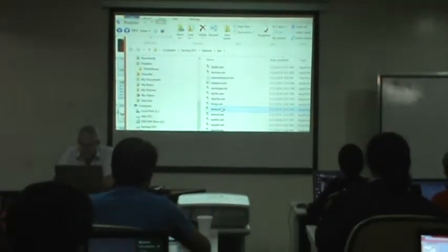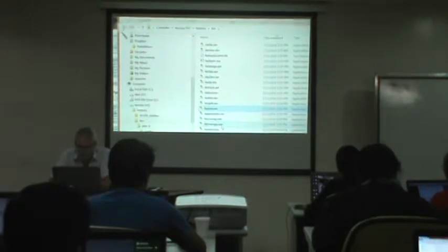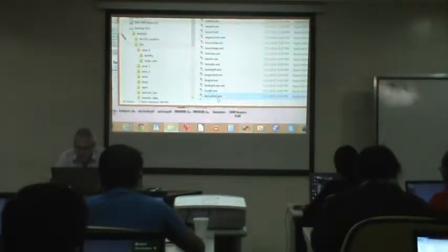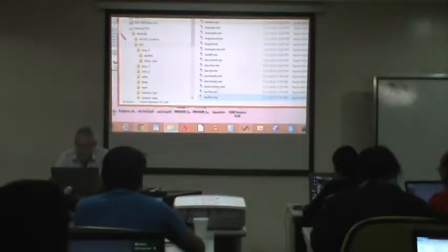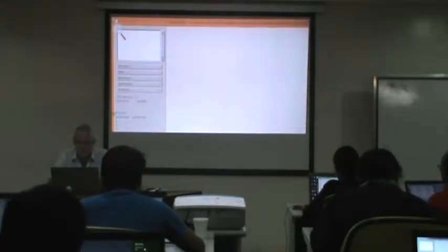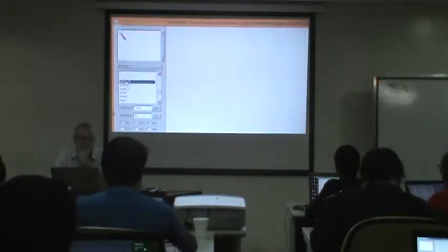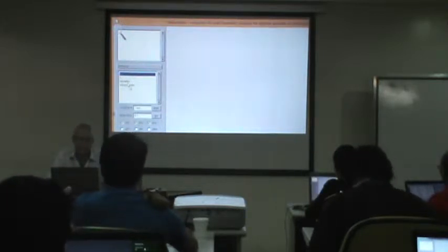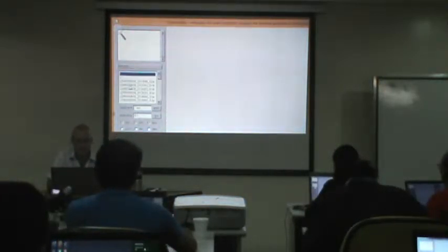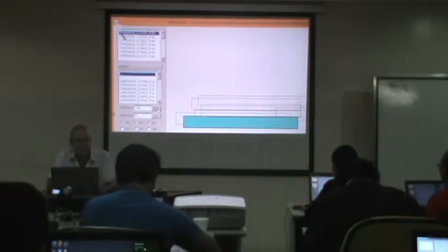Look for a tool that's called lasboundary. I found it right here. And again, load all the 7 LAS files. You could double click each one of them, or you could directly just use the wildcard and press add, and they're all here.